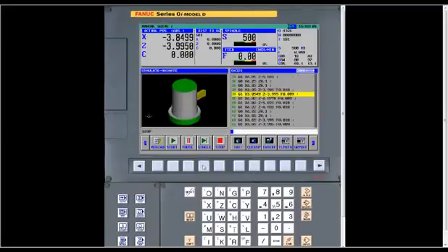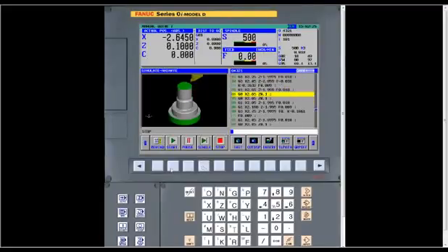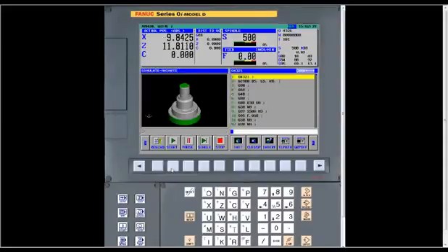It does a rough cut, another rough cut. I'm seeing it showing the tool, and I'm showing it like it would be on a VTL type machine. That's how I got it configured right now. See, it's going all the way through and cutting the entire part. I'm just going block by block at this point. Then if I press start, it'll do it much faster. And there's a simulation. Okay, thanks, Judy.